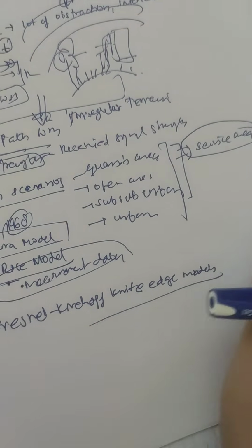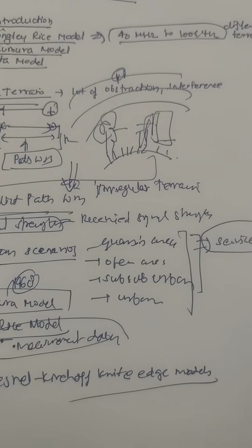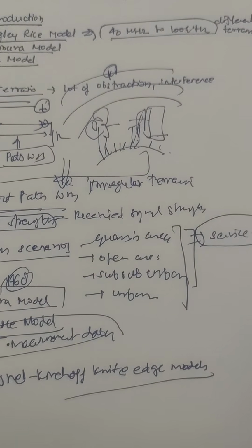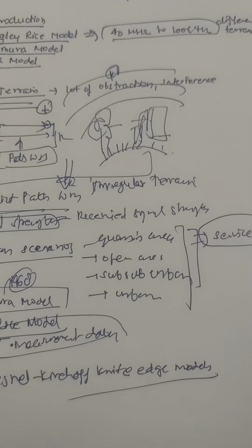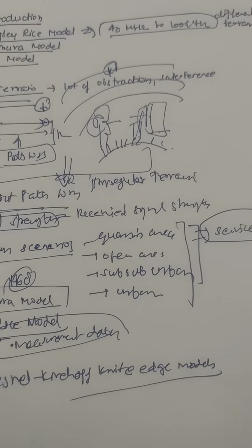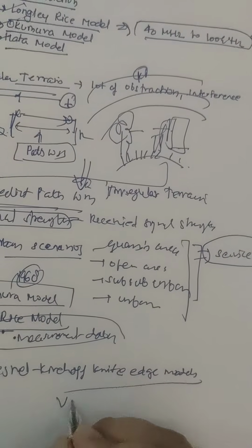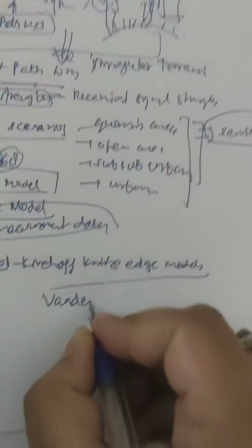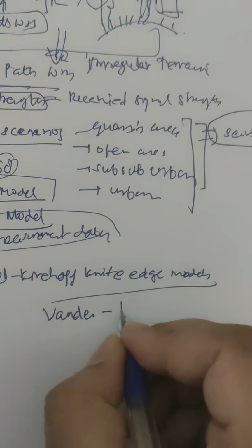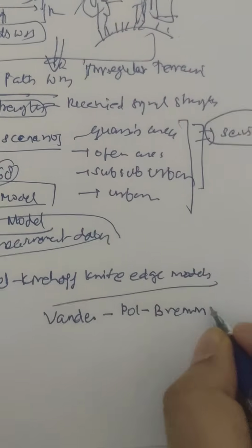Forward scatter theory is used to make troposcatter predictions over long distances, and the far-field diffraction losses in the double horizon path are predicted using the modified Van der Pol-Bremmer method.